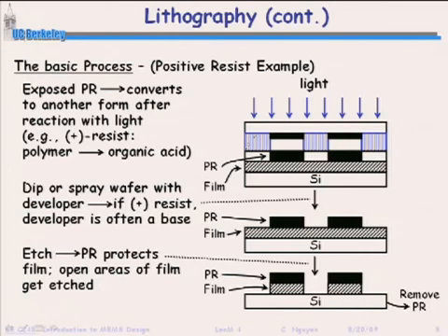Okay, if it is a positive resist, and there's such thing as a positive and negative resist, but if it's a positive resist, then when the light hits the photoresist, that's an area that can be removed. Okay, so that photoresist is weakened, I suppose, such that it can be removed later on, so that you're left now with photoresist patterns here that mimic the patterns that were on the mask. Okay, you then can go on with an etchant that then etches the film underneath that, so that now the film mimics the pattern of the photoresist, which essentially mimics the pattern on the mask. Okay? And you can make these patterns very small. Right? This is how we get our tiny resolutions.